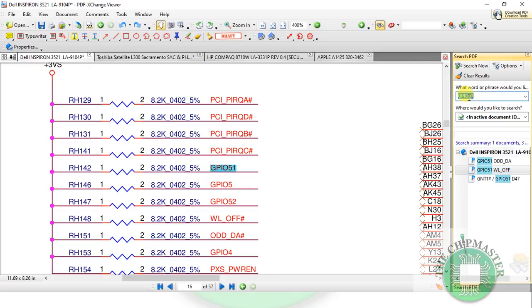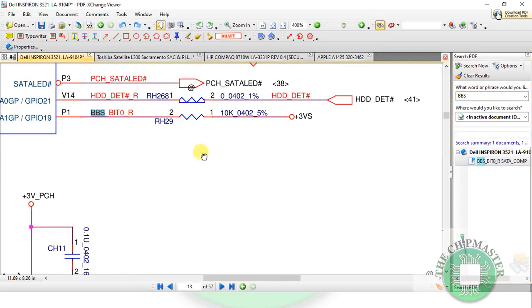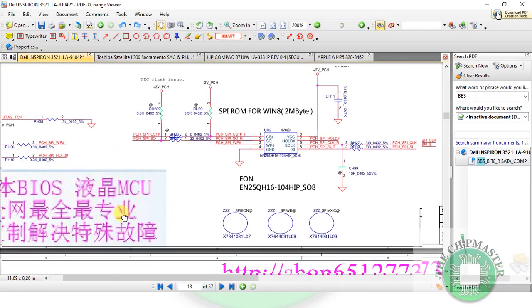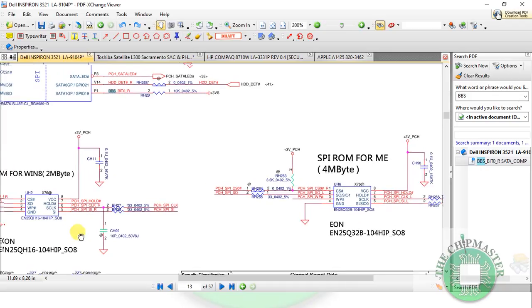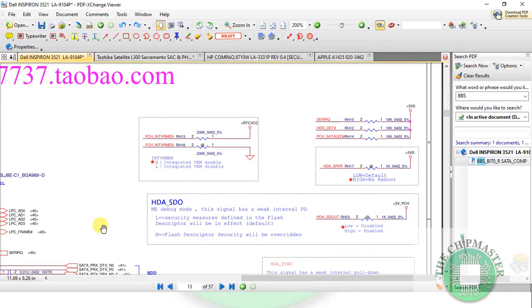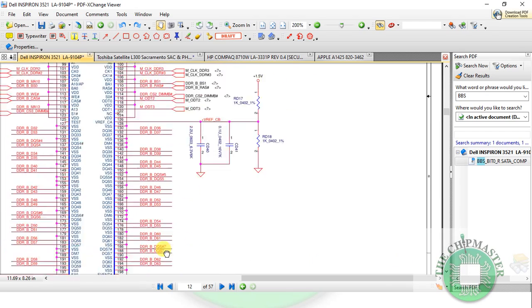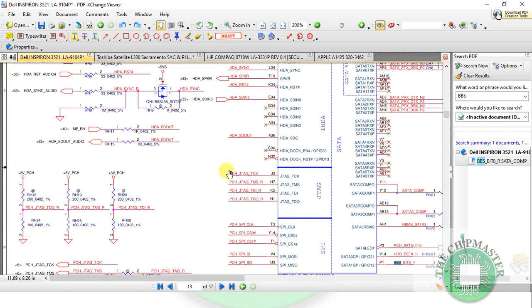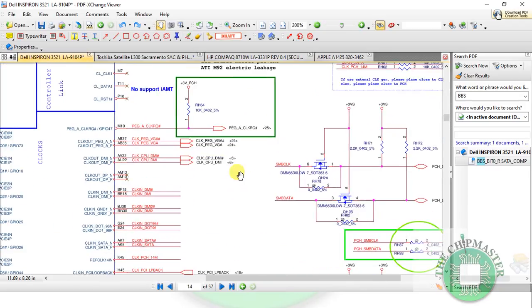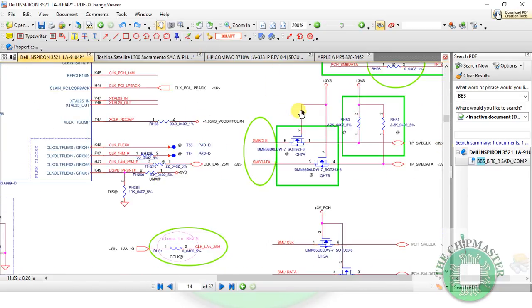So if I type in BBS, right, BIOS bootstraps, this is by default going to connect to the SPI bus to read its BIOS. Okay, the information is normally written on the schematic, but I'm not seeing it on this. So if these resistors are broken or corroded or having a fault, then you get no display because the CPU doesn't know where to go and read BIOS.